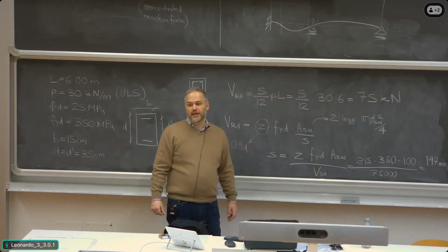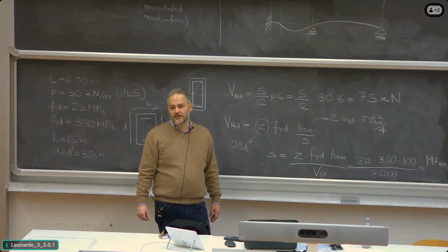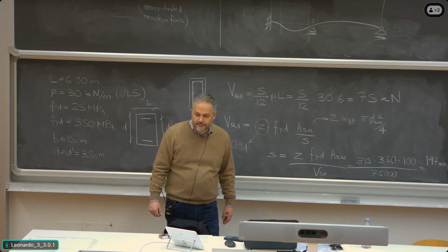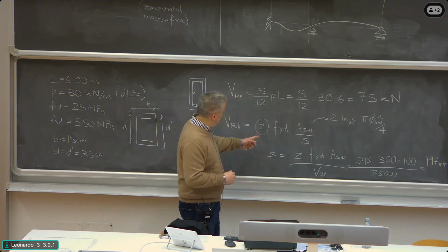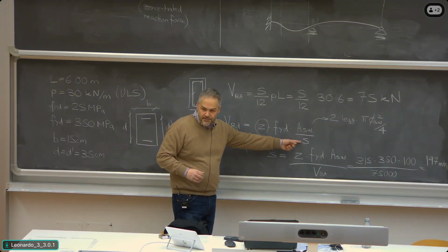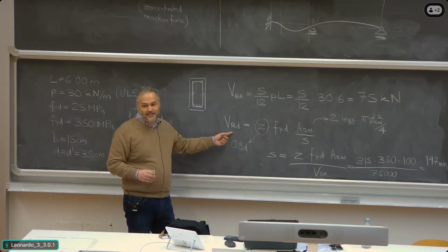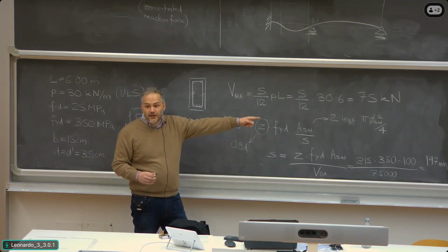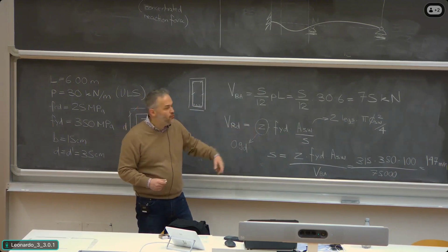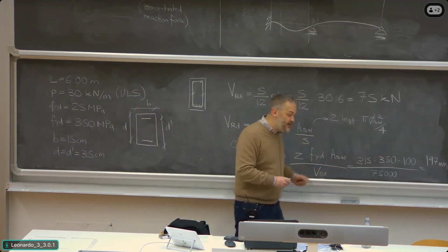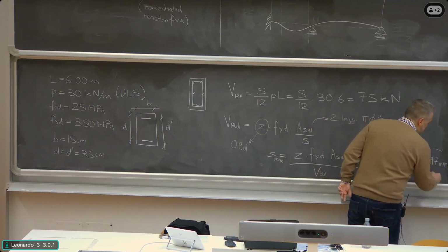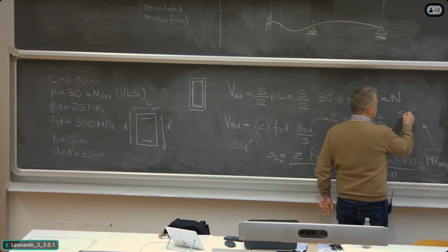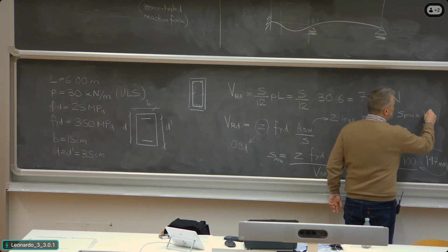This is not a number which we can provide in a design. We have to round it. The question is, do we round it up or do we round it down? In this case, you have to remember that the smaller the stirrup spacing, the higher is the resisting shear. So when you get the value of spacing, you round it down, which means this is the maximum value of the spacing, which means that the spacing we will then provide is 14 centimeters.